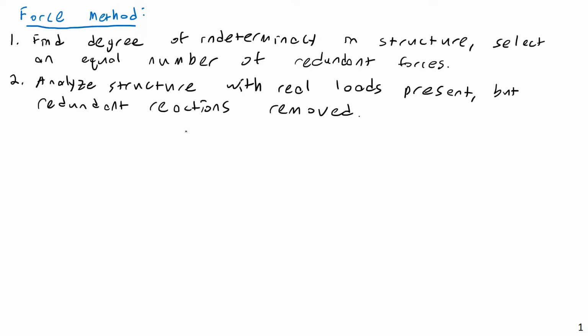So in the case of, say, a beam, if we had a redundant force at point A. If you remember previously in our discussion of beams, it was very common to have a delta A naught, and that would be the real deformation or the deformation under the real loads at joint A, and joint A would be the location of the redundant.